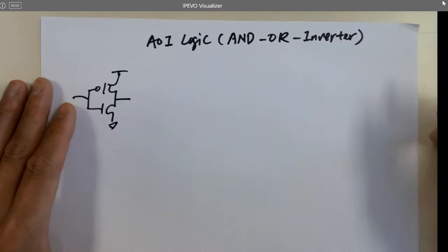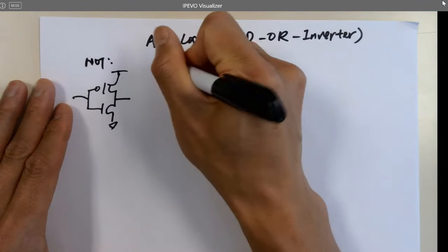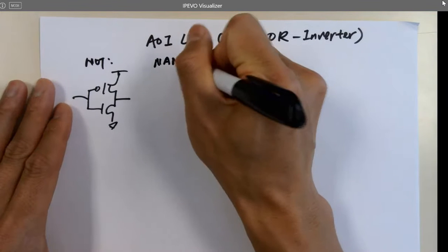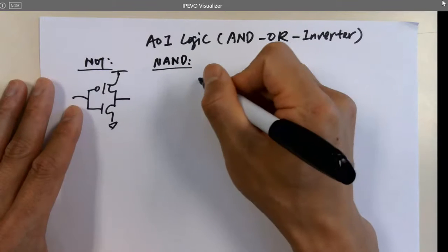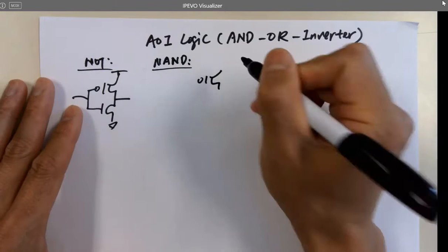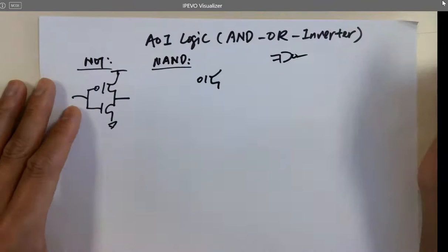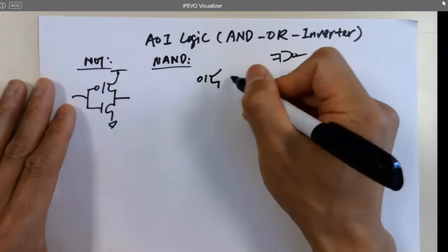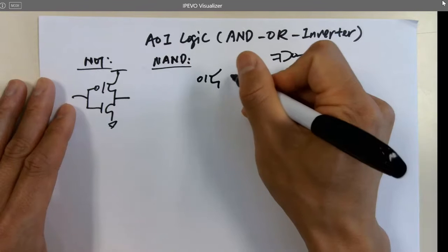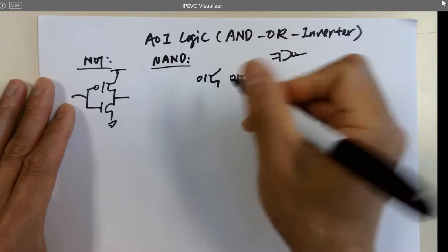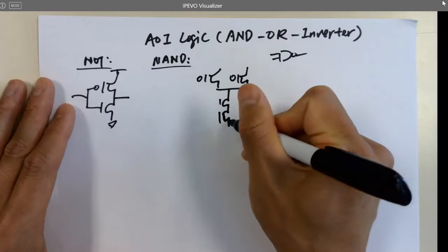Yeah, what about the NAND gate? And why do we do that for the NAND gate? So first, how many inputs for the NAND gate? Yeah, one output, right? So we need 2 transistors for each side, for 2 PMOS and 2 NMOSes. So I'm going to draw the schematic here first, and then we are going to go through why we do that.